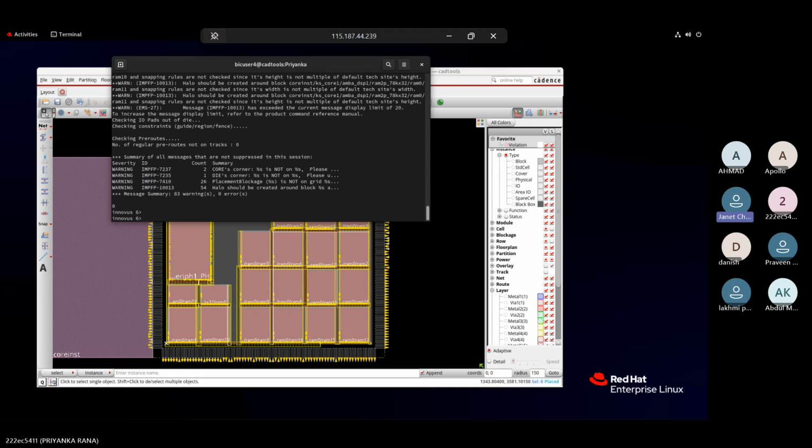Check F plan, space, then the greater than symbol. Type space, fplan dot rpt. Dot rpt is the extension for any reports like that, and fplan is the name you're giving. Give enter.